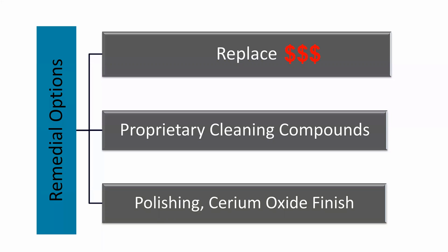As we already talked about, replacing the glass can be very costly. There are your glass sets, and they've come to cost a lot of money. Secondly, we have seen glass cleaning compounds, one of which was highlighted in a previous slide, that contained either silica or hydrofluoric acid that has done more damage than good when it's been used on the sides of building facades.